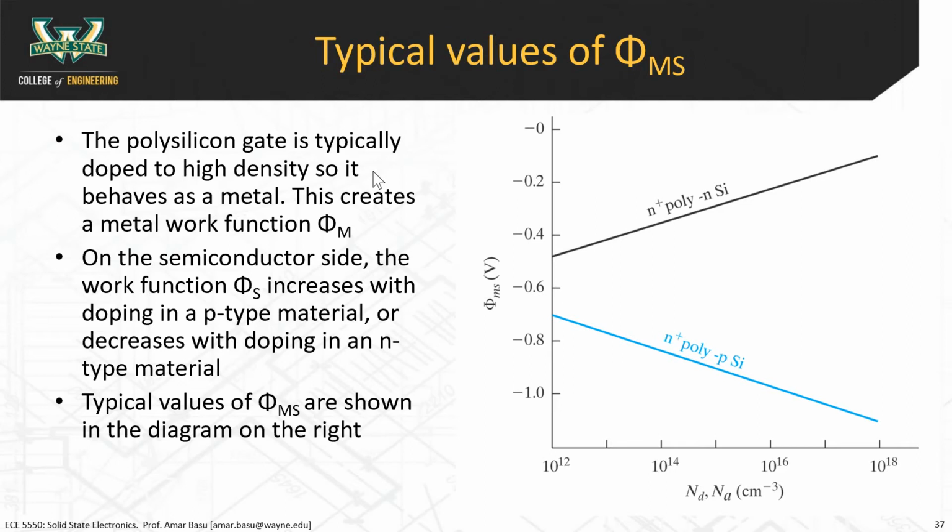So instead, they used a silicon material, which has a very high melting temperature, and they just used a heavily doped silicon material. They call it polysilicon. Polysilicon means it's not single crystal silicon. It's partly amorphous, partly single crystal. The fact that it's amorphous doesn't matter. It's just behaving as a metal. It just has to be very conductive, so as long as it's highly doped, it's good enough. We don't need to rely on the single crystal properties.